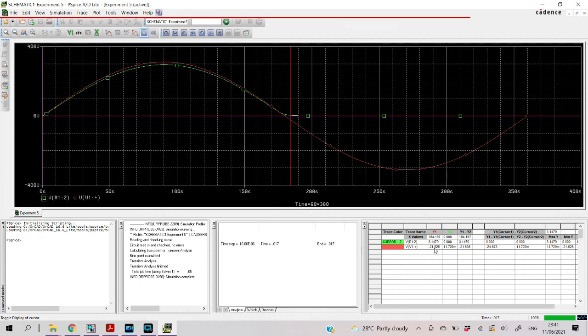No, no, it is 3.80. So our VO mean is approximately 0 since it is a half-wave rectifier. So the delta VO, trying to subtract 50.846 to 0, it's still 50.846.